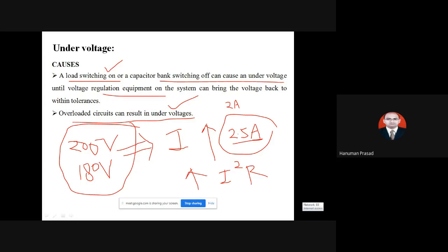और हीट से भी क्या हो सकता है? योर अप्लायंसेस में बी डैमेज. दैट मीन्स you do not require under voltage, you do not require over voltage. ना आपको ओवर वोल्टेज चाहिए ना अंडर वोल्टेज चाहिए. ओवर वोल्टेज हो गया, वोल्टेज ज्यादा हो गया, इंसुलेशन ब्रेकडाउन हो गया. अंडर वोल्टेज हो गया, करंट इंक्रीज कर जाएगी, करंट जब ज्यादा ड्रॉ करेगा, तो वहां पे I square R losses increase in the form of heat. तो दिस इज प्रॉब्लम्स ऑफ अंडर वोल्टेज. दैट मीन्स आपको ना अंडर वोल्टेज चाहिए ना ओवर वोल्टेज चाहिए. यू हैव रिक्वायर्ड 230 वोल्ट फॉर द डोमेस्टिक एप्लीकेशंस.